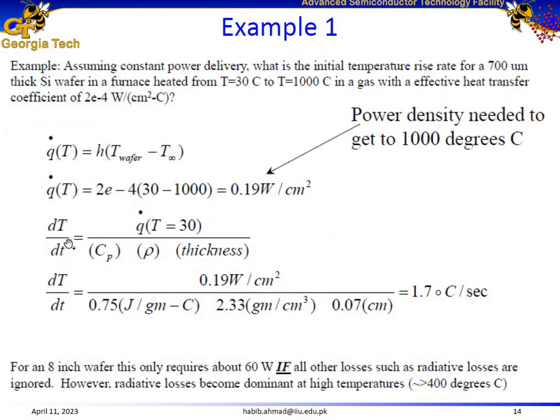Here is the formula. Rearrange it for heat flow per unit area, and this is equal to P divided by A. But then for P divided by A, the area goes to the denominator, and area times thickness is equal to volume. So replace it with P divided by specific heat times density times volume, and then rearrange it for power.